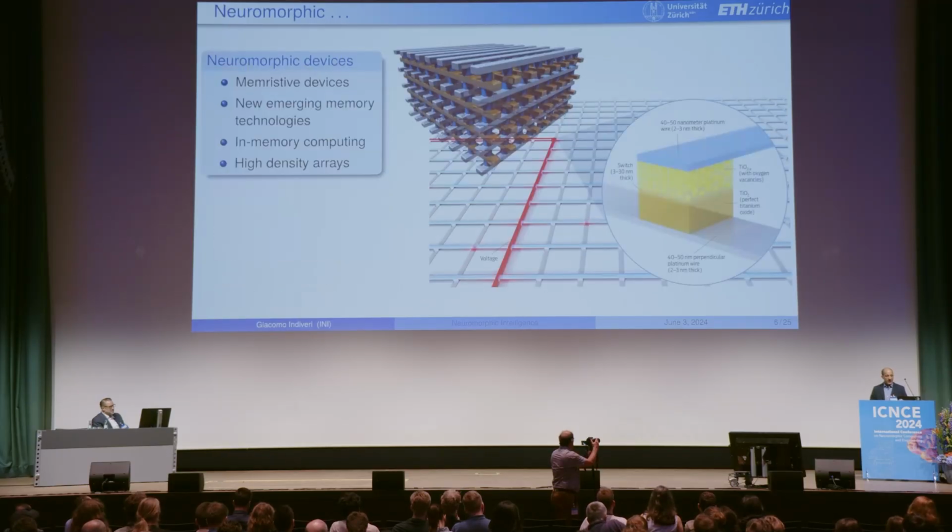But in 2008, Stan Williams, who will also be presenting here, made a very impactful publication on memristors. They found the missing memristor, and the community started to use the term neuromorphic to refer to these devices, as we've heard, that are two electrode devices that can store information in a non-volatile way by applying a pulse, like a spike, to the bottom and top electrode, with some variability, with some state dependence, stochasticity, so with properties that resemble, in many aspects, the properties of real synapses.